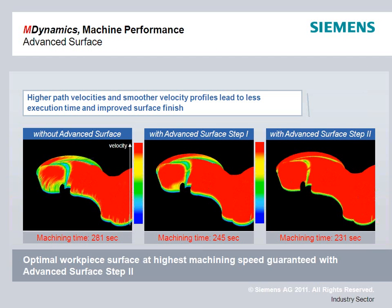So with Advanced Surface, what we've done is these are some standard test parts that we use internally to test our own programs. In these programs, areas that are red represent high path velocity, and areas that are blue represent slower areas. We basically just do a short coloring move over the top of this chess piece. So we bounce back and forth up over the top of it, similar to what you'd do with a mold and die part.